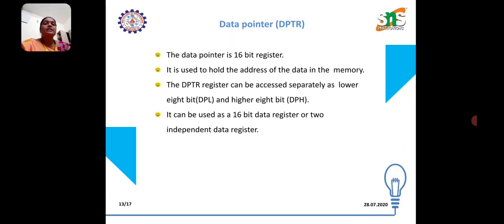The next one is the data pointer. The data pointer is a 16-bit register. It is used to access the external memory address. Even though it is a 16-bit register, it can also be accessed as two 8-bit registers, that is DPL and DPH.